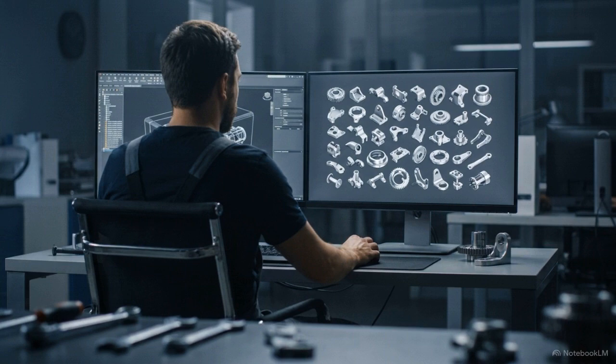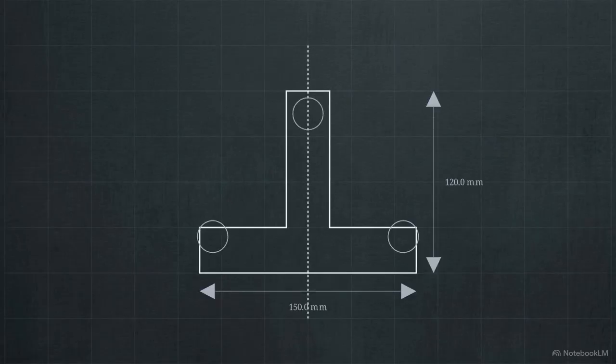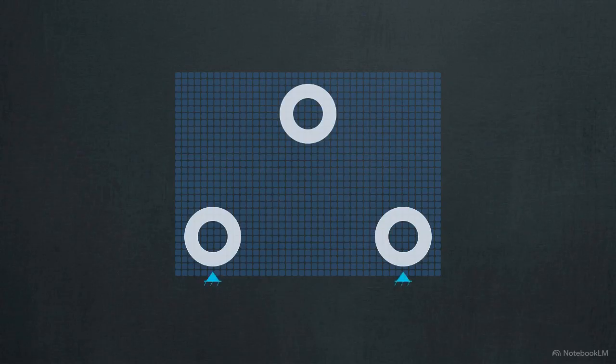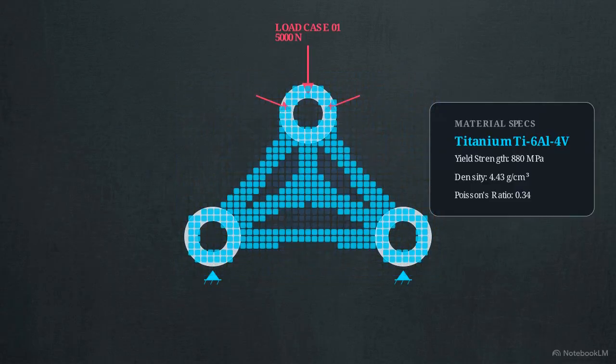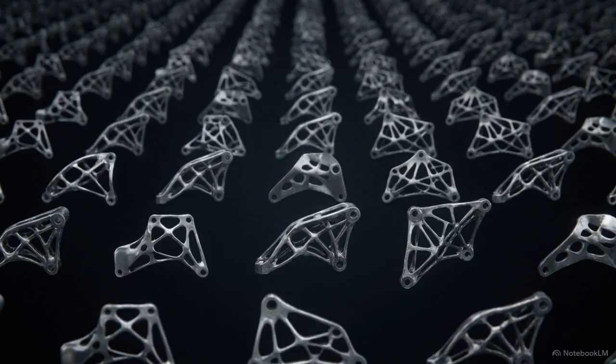Artificial intelligence has quietly moved into mainstream CAD software, making its way onto the mechanical engineer's workstation to alter how parts are initially shaped. Instead of drafting a single geometry line by line, engineers now use generative design. They input the physical limits, define the materials, and set the load cases, the specific maximum forces the part must survive. The software then generates vast families of candidate shapes.